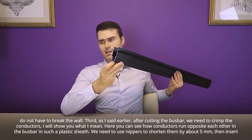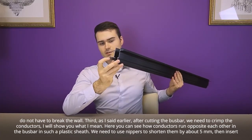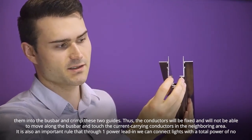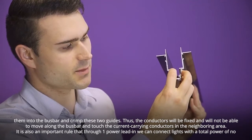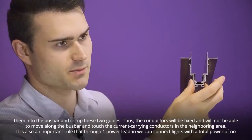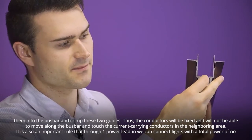Here you can see how conductors run opposite each other in the bus bar in such a plastic sheath. We need to use nippers to shorten them by about 5 mm, then insert them into the bus bar and crimp these 2 guides. Thus, the conductors will be fixed and will not be able to move along the bus bar and touch the current carrying conductors in the neighboring area.